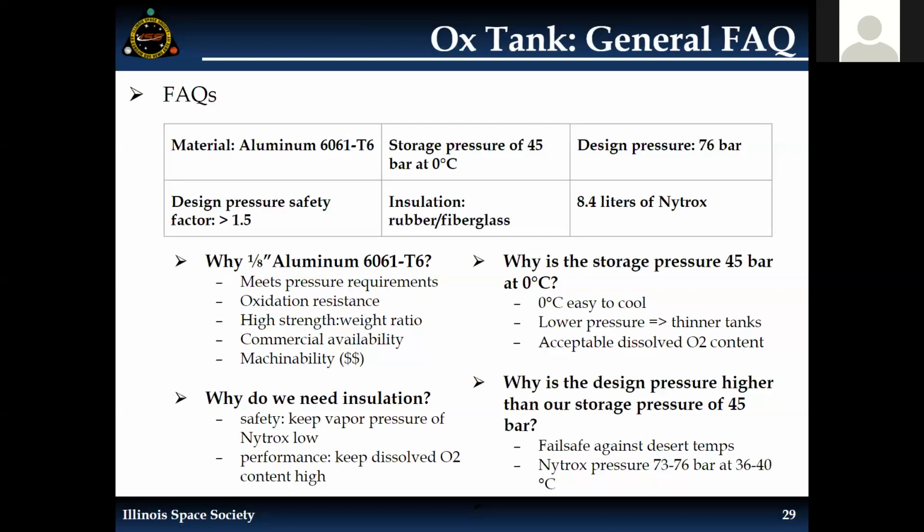But to get the liquid oxidizer to accelerate through the system, you need to have a pressure drop. A pressure drop is just a difference. So Nick, you mentioned 45 bar is upstream. Upstream is further up the system, the oxidizer tank at 45, and downstream it's 30 bar. So it's going to move from high to low pressure. We'll get much deeper into that, but that's basically it. Keeping track of pressure drops is a very big part of rocket engine calculations. Awesome, thank you.